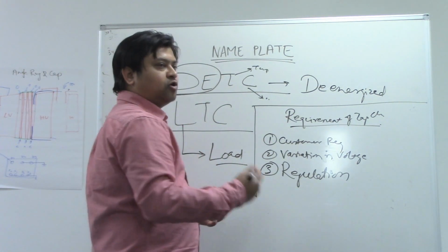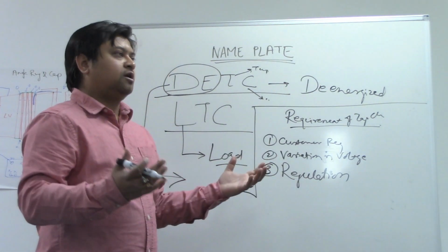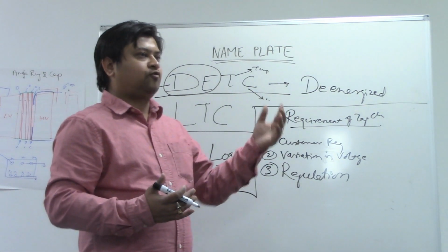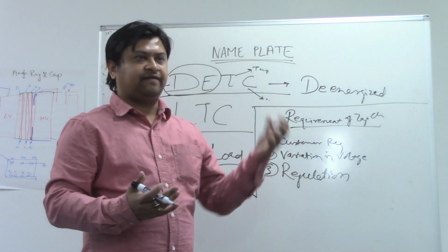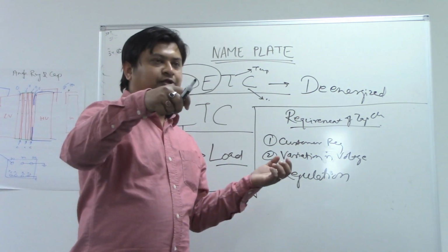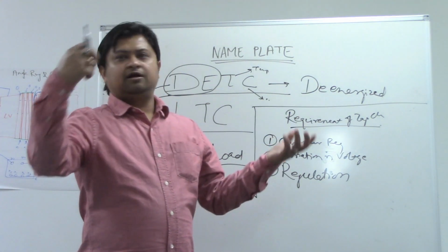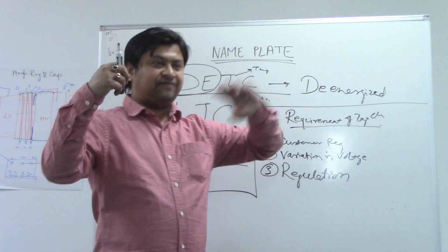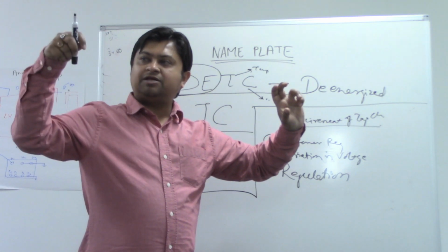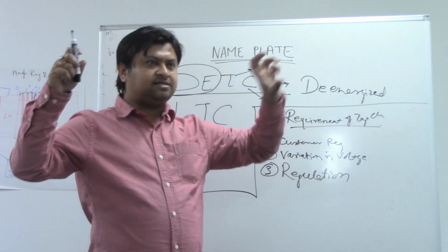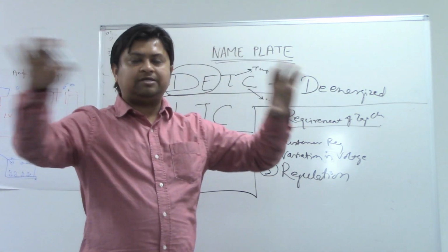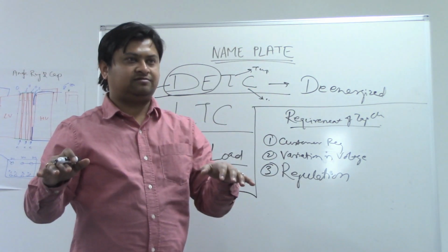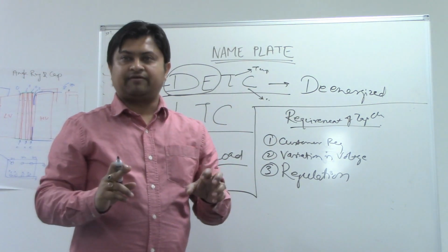The customer doesn't want to run at, say, 25 kV. Let's suppose there is 25 kV, and once he is adding the load, he may get 25.6 kV, right? But he doesn't want to run at 25, because if his requirement is 25.6 and he runs at 25, the whole network will go under voltage, right? That could damage your equipment.